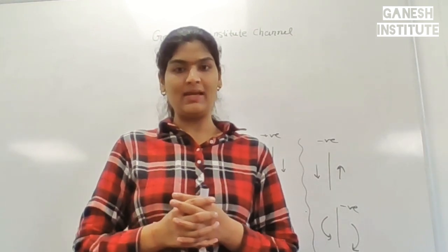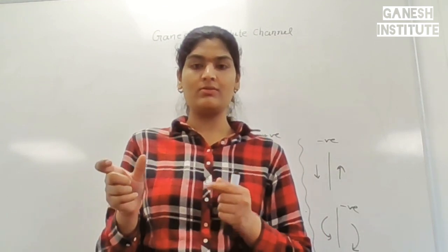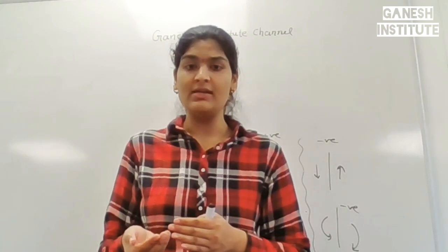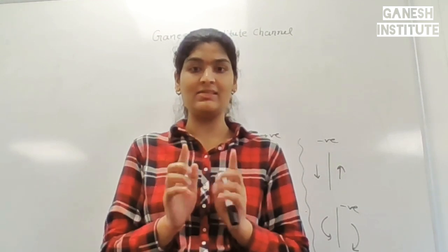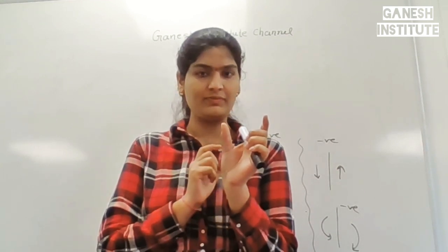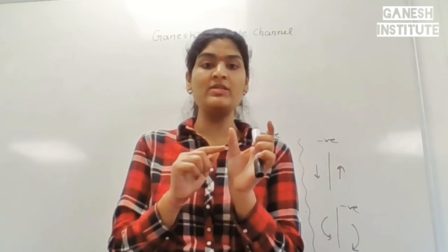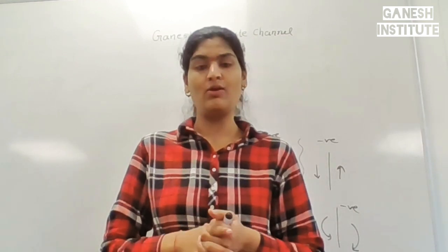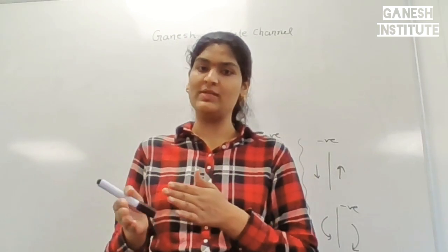How can we evaluate any bending moment and how is it different from the bending force? Force is just a force, that means its unit is Newton. However, the moment is the force exerting along with the distance. We have to consider the distance as well. So let's say between two points the force applied is F and the distance between the two points is A, then the moment will be force times A, and that will be Newton meter or kilonewton meter, whatever it is. Distance multiplied by force.